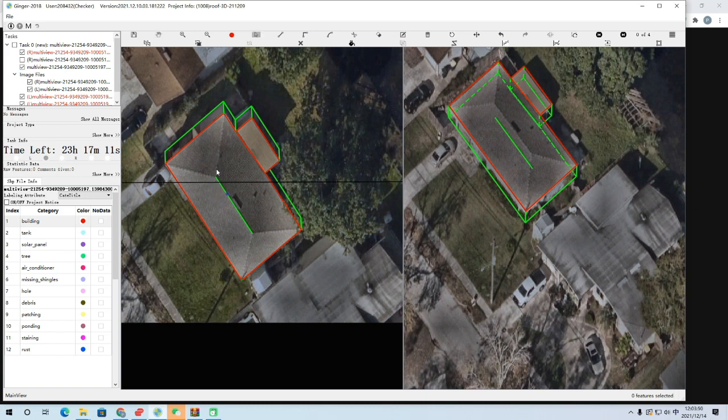I will recap again. This roof ridge line is the most important part of the roof structure project, and it is the first thing you need to do when you draw a roof structure, because it decides the height and 3D relation with all other roof structures in this building. So every time you draw a big or small part, you need to find out where the roof ridge is. And also, when you draw the roof ridge, it has to be parallel to the sides of the building.